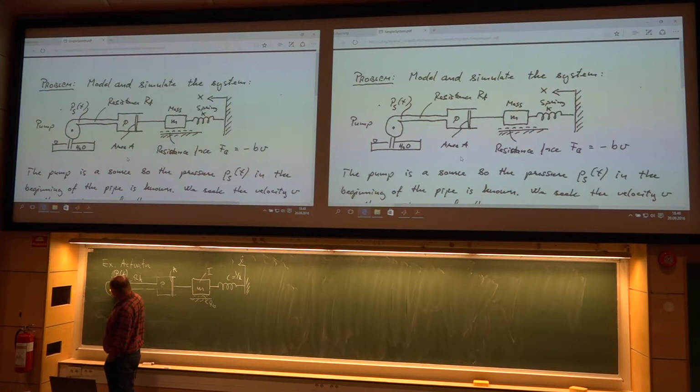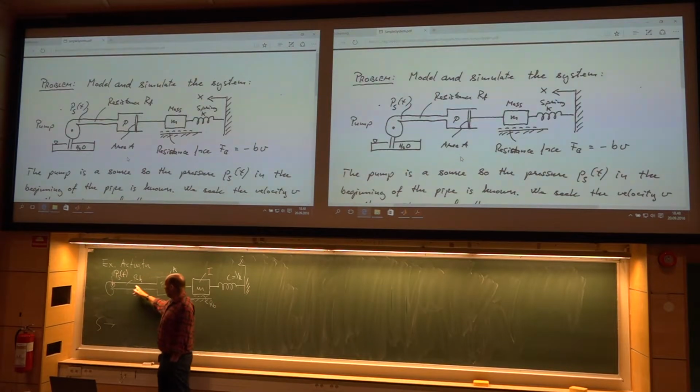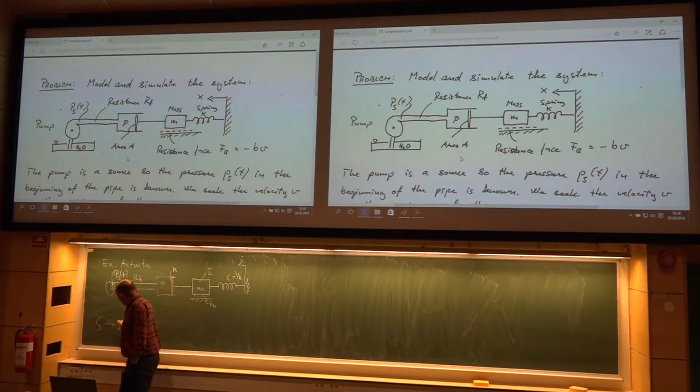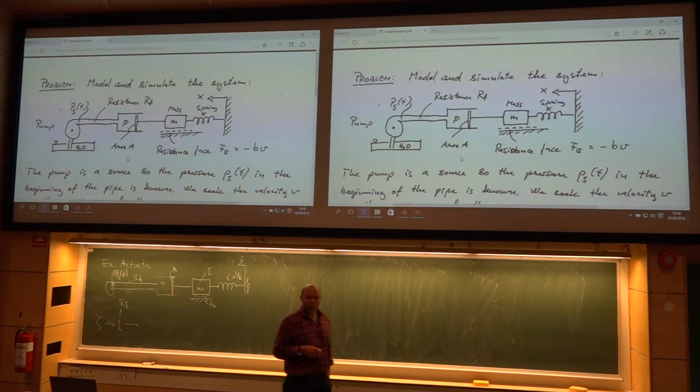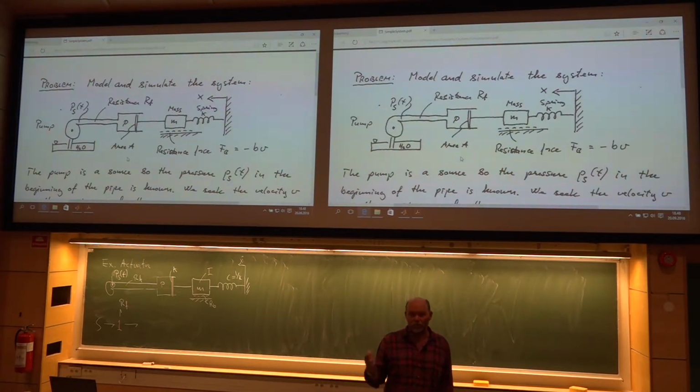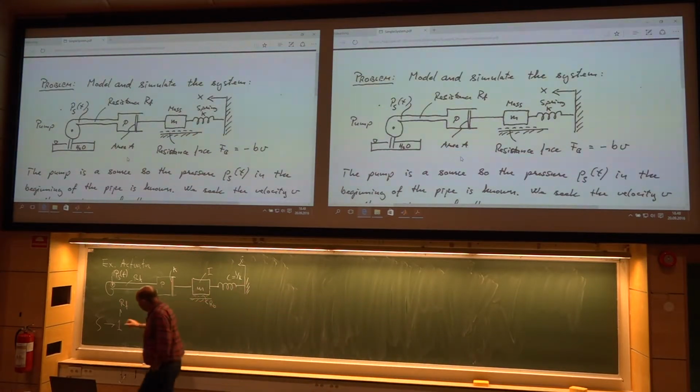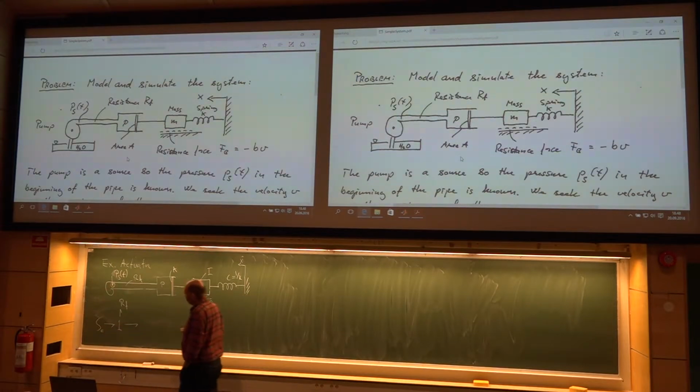Okay, here we have a source hitting something that has its own velocity. We have resistance, but the flow goes straight through it, hence it will be a one junction for this resistance RF. Everything has to go through the pipe here. And then we continue like that. What kind of source is it? Well, we know the pressure. The pressure is given. And in fluid, the pressure, that is the effort. So this is an effort source.